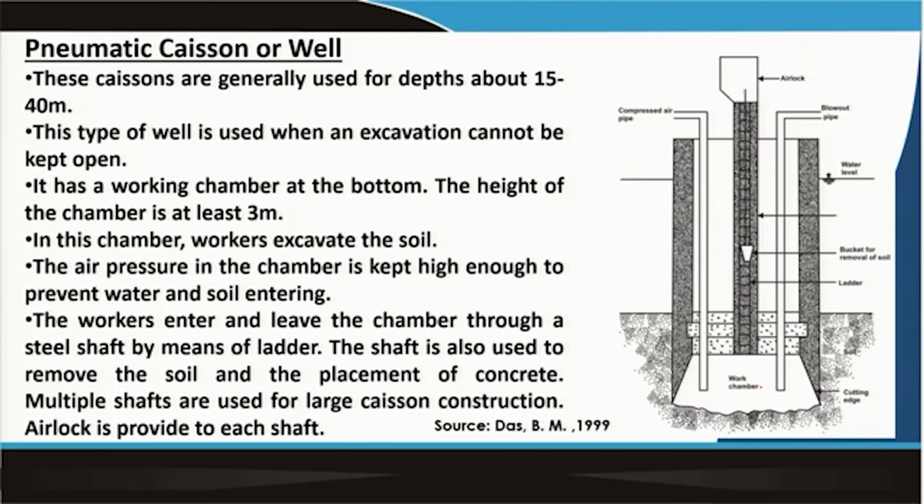pressure in the chamber is kept high enough to prevent water and soil from entering. As I mentioned, there is a possibility of soil and water entering the excavation. So, high air pressure is maintained within the working chamber, so that water and soil cannot enter. That is why we have to take care of the health of the workers, and if required, there will be a rotation of the workers within the working chamber. They cannot work for a long time within that chamber.